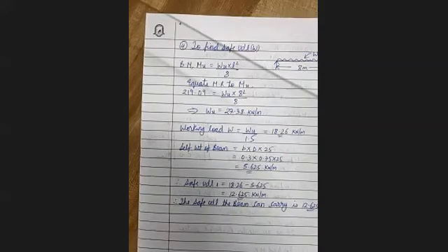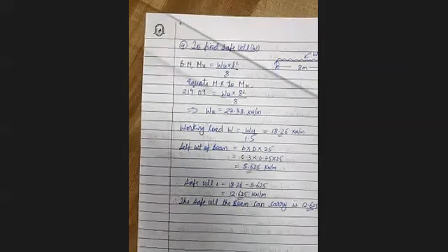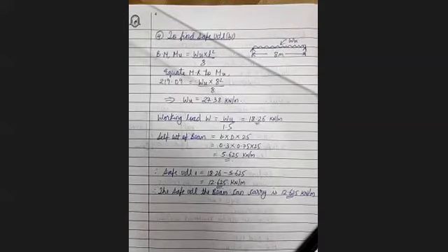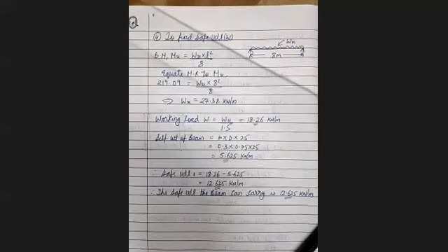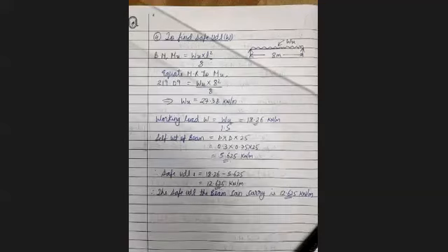Calculate the MR of a rectangular section 450 by 600 mm reinforced with 3 bars of 25 mm dia on the tension side, placed at an effective cover of 50 mm.